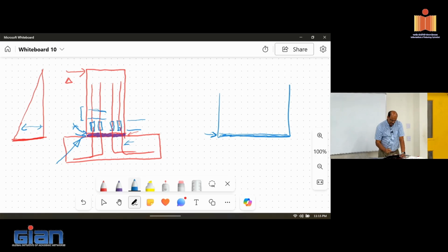There will be a drastic difference in terms of how the crack pattern develops. It also depends on how long your coupler is, exactly where the coupler is located, and the moment gradient of the system. So in other words, the aspect ratio of the wall. All of that plays in.